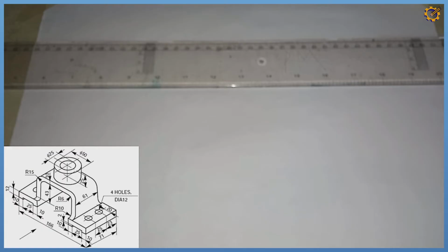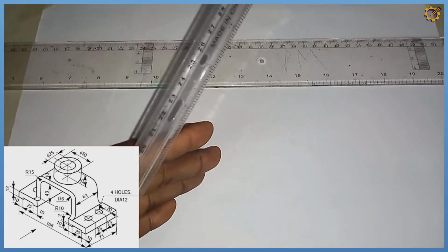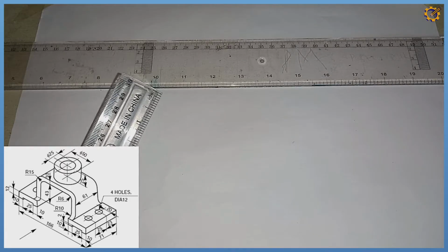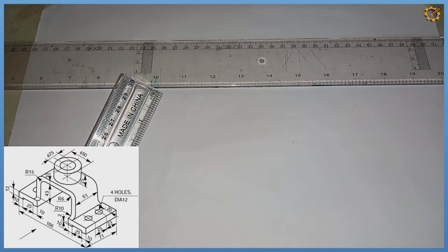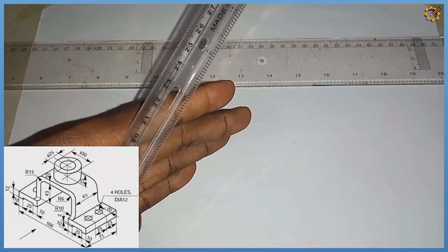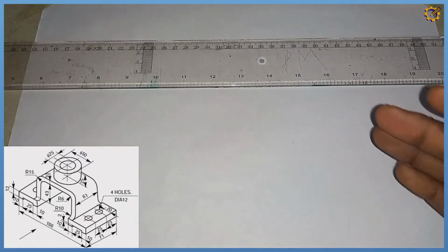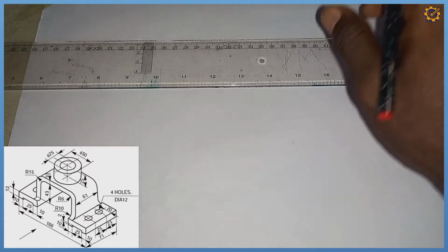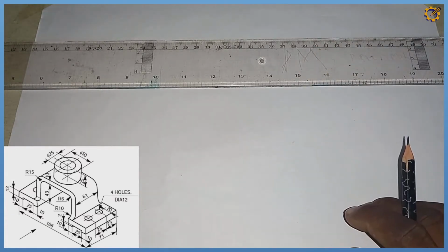Alright, for today we'll be producing the object on the screen, which is a machine component, in first angle orthographic projection. Taking the direction of our arrow, which is towards this area, as the front view. Based on the principle of first angle orthographic projection, if our front view is right here on the object, then automatically this other view is our end view. For this reason, our front view will be seated right here, our plan underneath, and our end view right here.